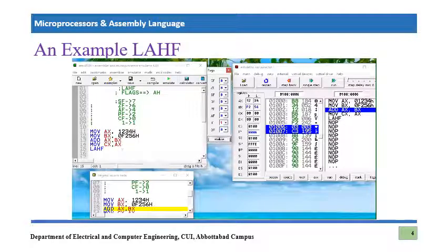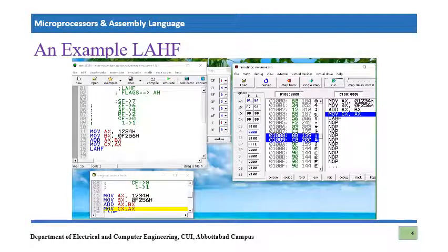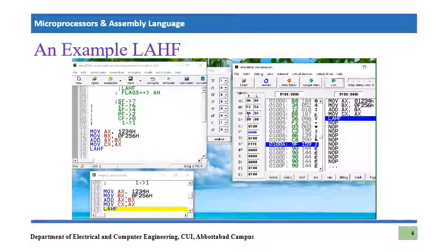So now what we are going to do, we are going to add. Okay, the result is added here, 048A. Look, the carry flag is high, the remaining bits which are of our interest are 0, so we know that only one bit is our interest and it is equal to 1. And now we are going to save this result, which is 048A, into CX. So let's perform. Okay, the result is moved.